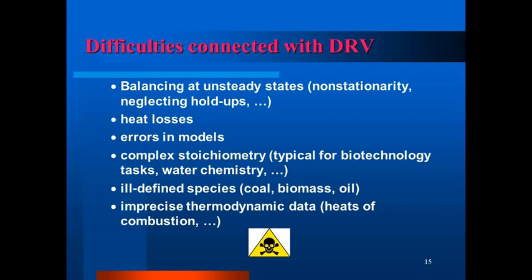The application of data reconciliation is not without problems. Several possible issues should be watched carefully. The first important problem can be the behavior of a plant in time. In classical balancing, it is supposed that the production process is at a stationary state. Data processing system averages values of fluctuating variables and uses the averages in further data processing.